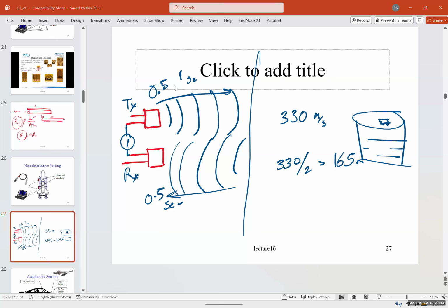So if an ultrasonic sensor shows a distance of 1 meter in Houston, if you bring the same thing to Amarillo, it's going to show you something different. It's going to be a little bit of error. So you have to adjust that. Previously, we had a potentiometer pot that we could adjust it.